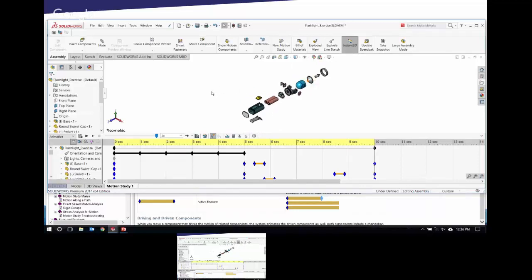You just mentioned the playback speed, is there a way to scale? Yeah. If you take this key point at the end of the animation, at the very top of the Motion Manager tree, hold down Alt on the keyboard and then drag that, it will scale the entire animation. No way to scale a subset of the animation though? I don't think so.